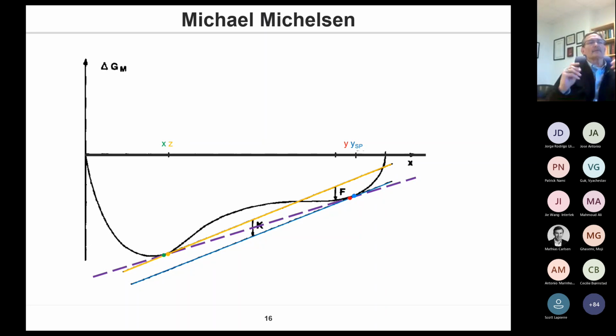But when you have 10 components or 50 components, obviously you can't do a graphical representation of this. Instead, he came up with an algorithm for doing the stability test in a very methodic way, and that generally would always find either a solution that said, well, the current feed composition appears to be stable. We can't find any composition that is moving this mixture into a two-phase system.